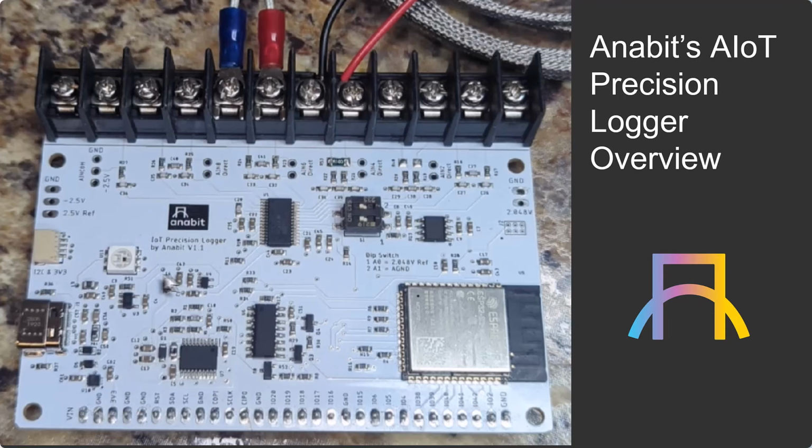And then we have put a lot of design effort into the power system. So this ADC can make bipolar measurements. So plus 2.5 volts to negative 2.5 volts. And so we create a negative bus from the input of the 5 volts. We also have a lot of filtering on these power rails. So by the time our power supply voltages get to the ADC and the programmable gain amp, they're very low noise. So we do not affect the accuracy or the resolution of our measurements.